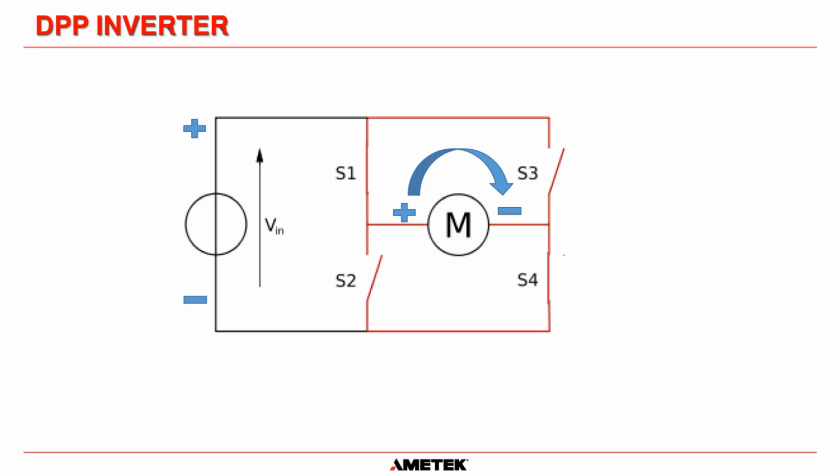It uses what's called an H bridge, because it looks similar to the letter H. The easiest way to think about it is we have four switches in an H bridge, S1, S2, S3, and S4. Rather than supply a transformer in this circumstance, just to give you an idea of how it works, we're going to supply a motor.